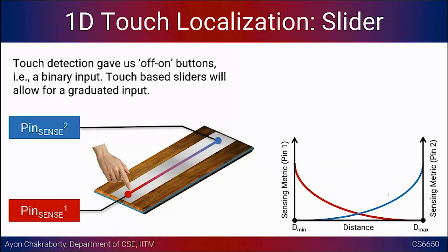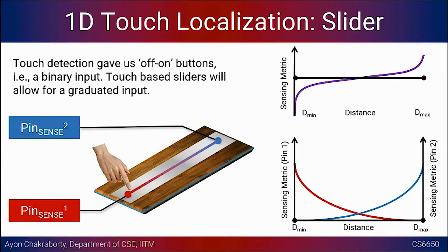So based on this particular data, you can always self calibrate the system, right? Whatever object or whatever material you are going to use for the touch, these 2 graphs are going to look the same. It is just going to be an exact opposite, right? And one simple heuristic that you can use is simply the difference of these 2, right?